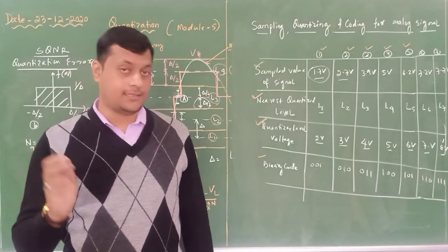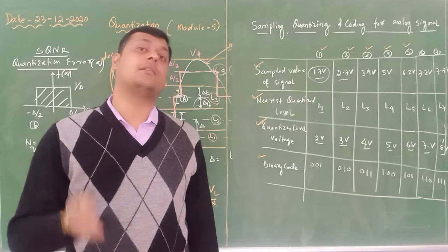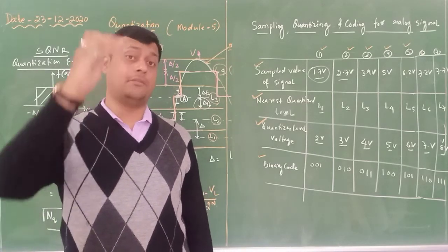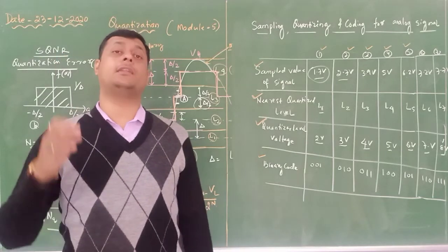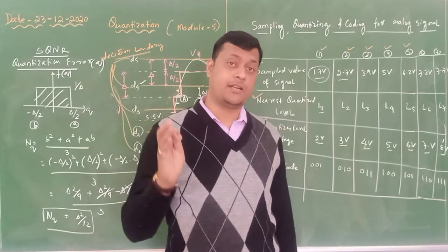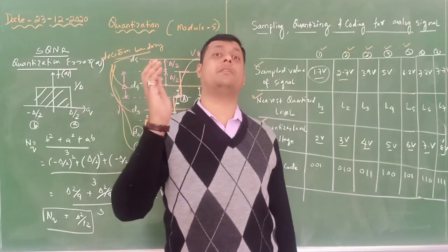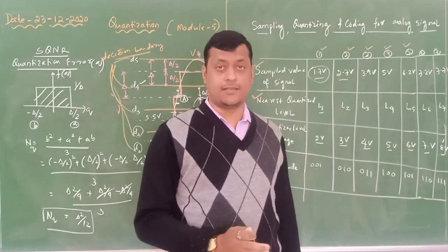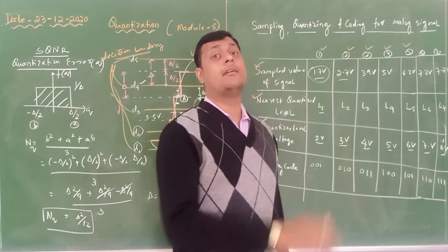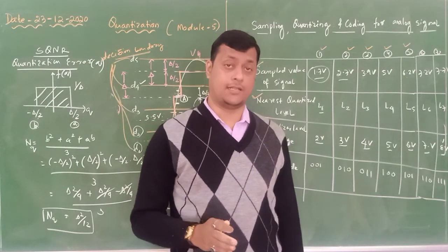Pulses are quantized. Quantization means some discrete potentials will be available, the quantization level will identify the rounded-up value, and each level will be assigned binary data. Binary data is going to be transmitted in a parallel manner. You need to convert that parallel to series. If you have converted parallel to series, that is called pulse code modulation.